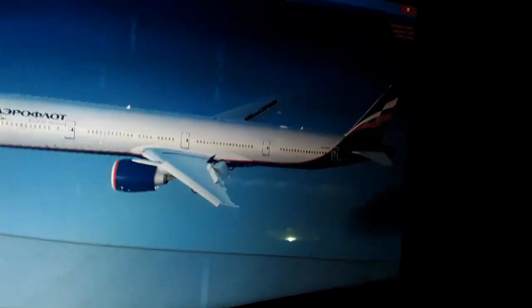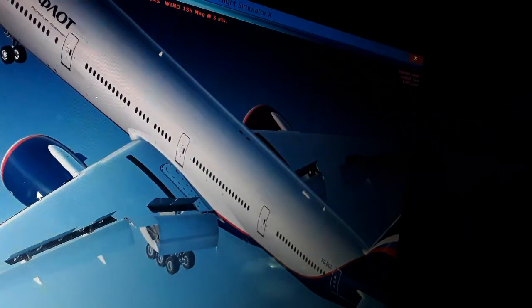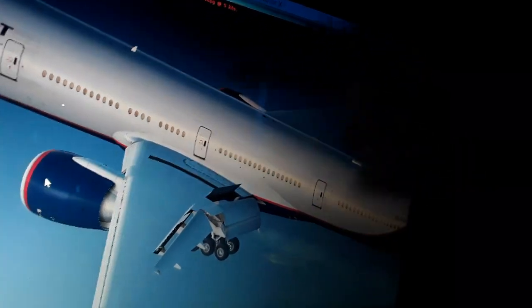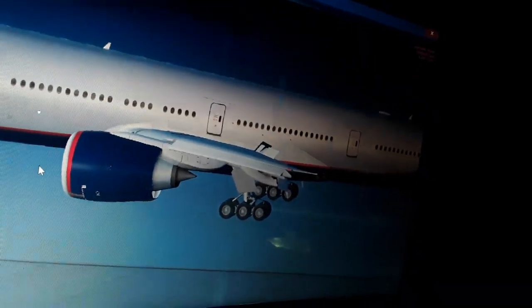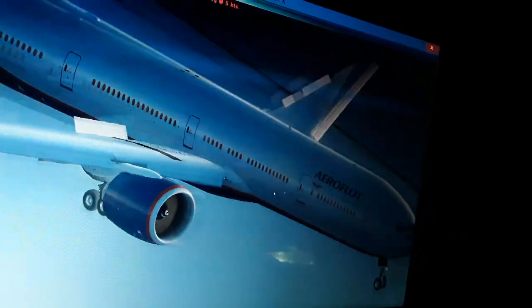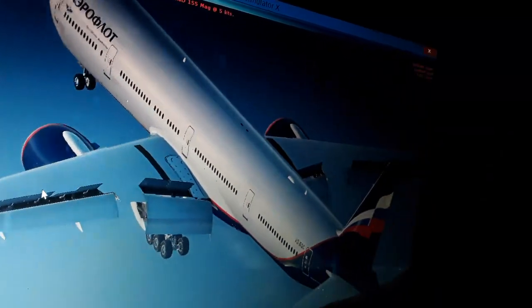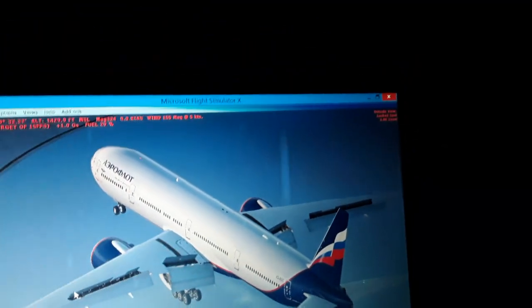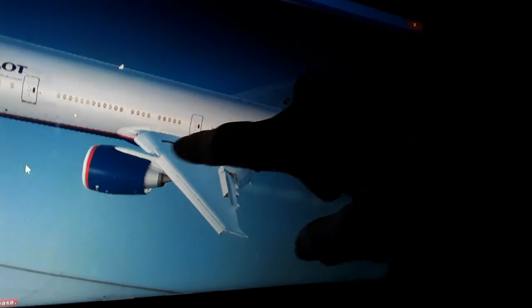So we have the leading edge and the trailing edge. You can see some other components. We have the mean aerodynamic chord of the wings. If we position at 25%, we can find the maximum aerodynamic lift position. It's also the position where the stall begins, where the aircraft starts to stall and loses its ability to fly. So the maximum aerodynamic lift position, also the center of gravity of the aircraft and the center of geometric positioning. So aerodynamic lift, a maximum, and center of gravity here.